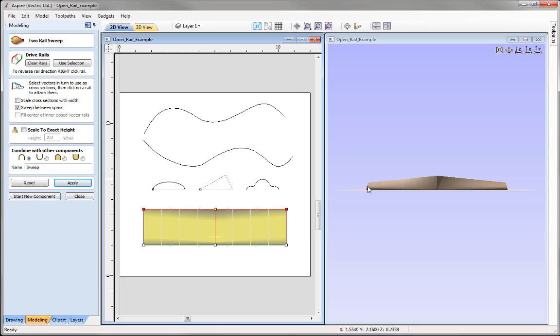So we're going up from this point here straight into the angled profile, straight down, straight in to the curved profile there. We could undo those, so I could simply come back, right click, smooth and press apply, and then right click, smooth, press apply. You can see we're coming into nice smooth transitions now. Right click on this one here, smooth, and then press apply. And you can see that even though we just created very subtle differences, it's just another way for us to control the shape that we're creating here.